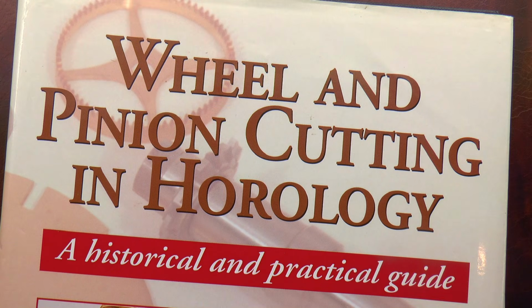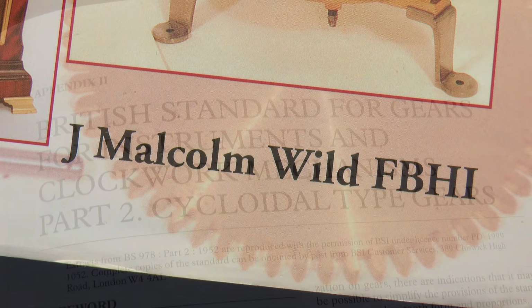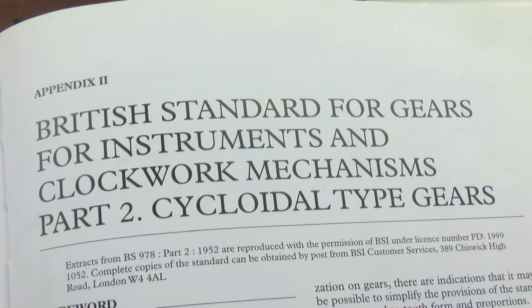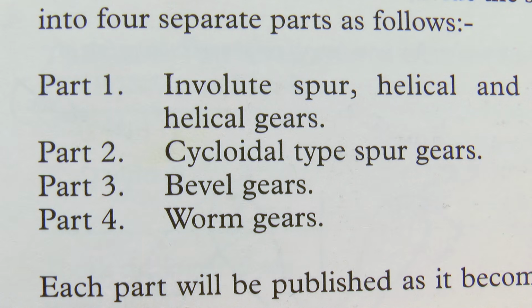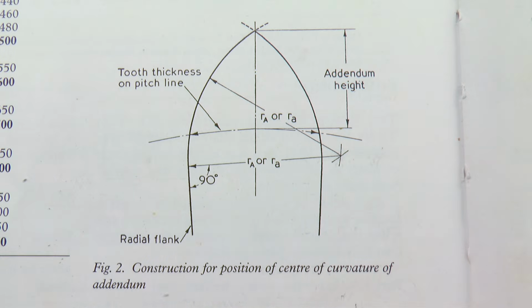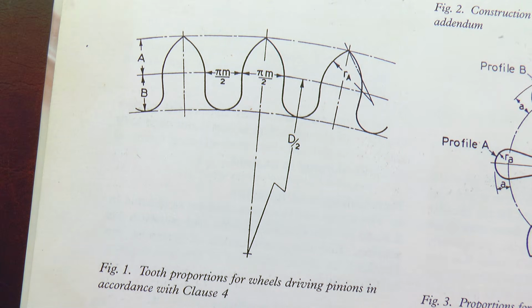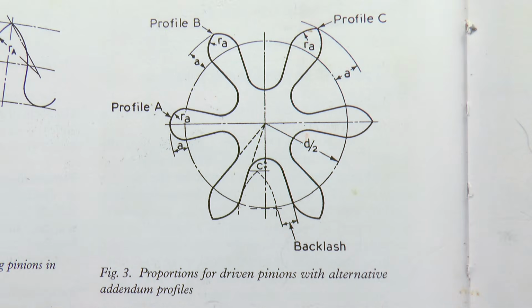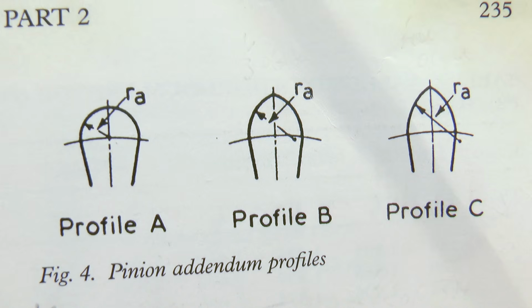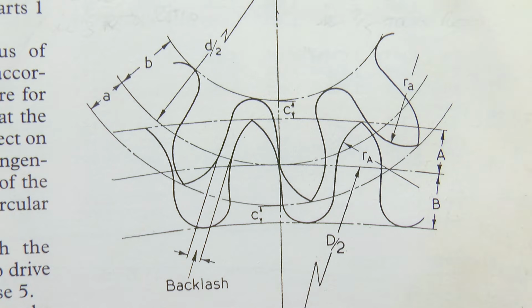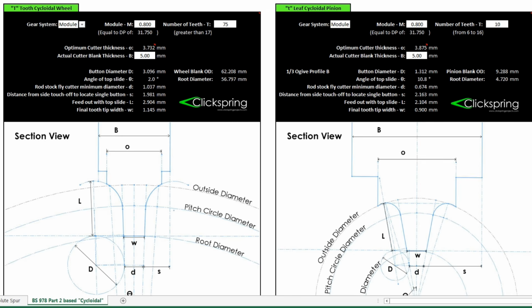And this is where we get our first break. If we look at the text of the cycloidal standard, we see that our curves are in fact not cycloids at all, but rather just simple radii. When the standard was drafted, it was recognised that a radius was not only a good approximation for the cycloidal curve, but that it would also enable much easier manufacturing processes. The rest of the geometry is defined in the standard, using straight lines or otherwise practical elements. So right away we know that we can make this profile, because we can certainly generate an accurate radius in the home shop. Now we need to know the dimensions and how to bring it all together, but they're just numbers, all defined in the standard and presented in this calculator.